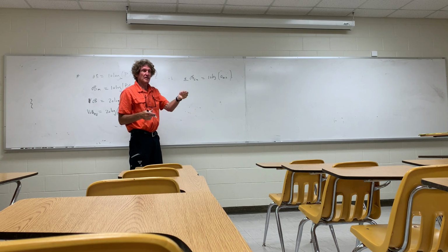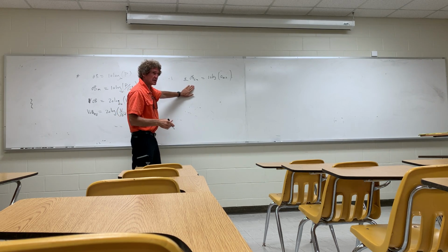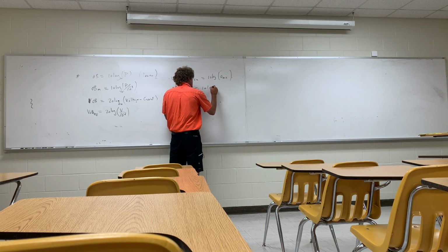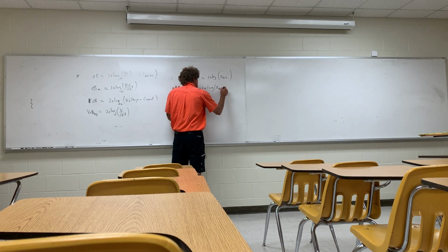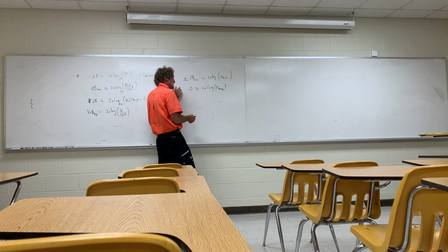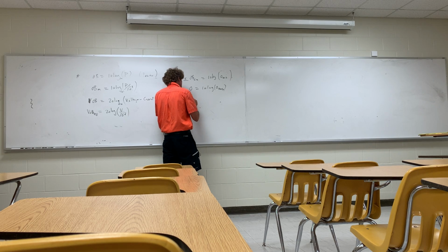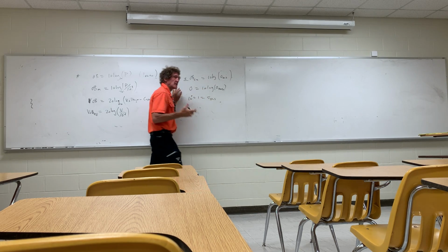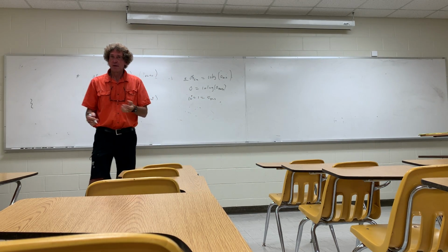Now, 0 dBm, we put a 0 over here because it's given in dBm. 0 would be 10 times the log of sigma RCS, right? Divide 0 by 10, you get 0, right? Take 10 to that power. So 10 to the 0 is 1, which is sigma RCS, and that's the linear value.